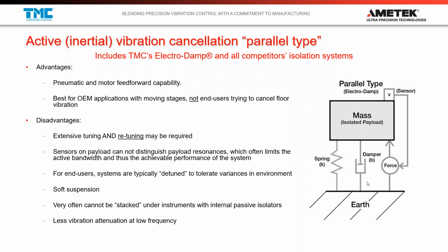See, the system can't tell whether it's sensing floor vibration or payload vibration, so it tries to cancel everything. And that could lead to a system that might have stability problems. And in order to get better stability in a parallel type system, you find that you need to start to reduce its effectiveness at certain frequencies. So it takes a fair amount of tuning to get one of these systems to really perform at a high level, and therefore they can tend to fall out of tuning very often.